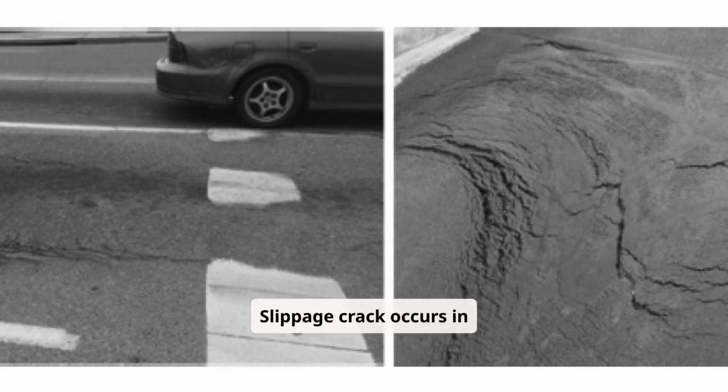Slippage cracks occur in asphalt overlays with lack of tack coat or poor bond between the old surface and the new overlay. They also occur due to excessive deflection of the underlying pavement structure under the compaction equipment or haul trucks. As the roller or truck passes, the surface of the pavement gets tension, forming the slippage crack. Removal and replacement of the affected area is the only solution for this distress.